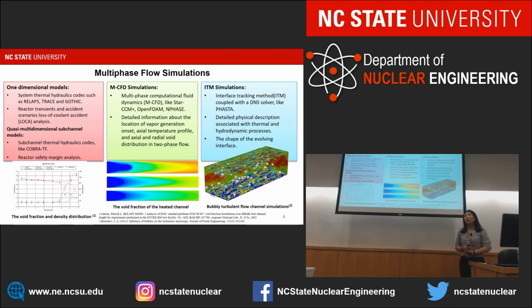Recently, interface tracking simulations, basically the direct numerical simulation solver coupled with the interface tracking method, have been introduced to multi-phase flow research. This type of simulation, as we could see here, is able to resolve the instant temperature and velocity field at and around the interface. You could see the bubble interface here. And it also provides detailed information on local phenomena.